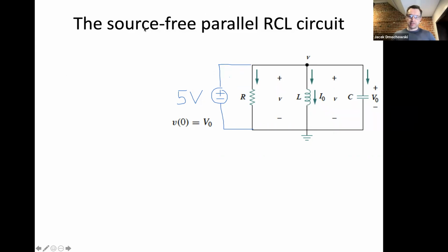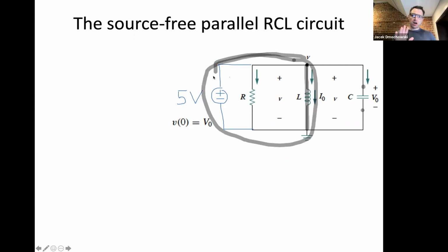So if I draw kind of a thick dark line here like this, if I short this inductor, then nothing's going to flow through the resistor. And this is an open circuit, right? This is an open, so this completely comes out. And basically the current takes this path, right? So that's where we are right before time zero.